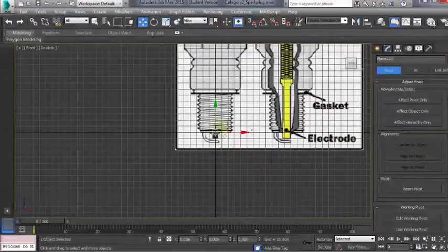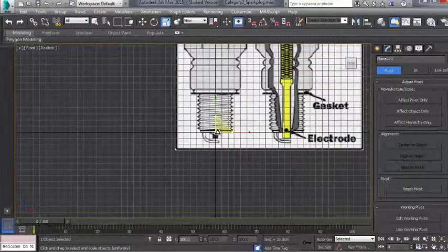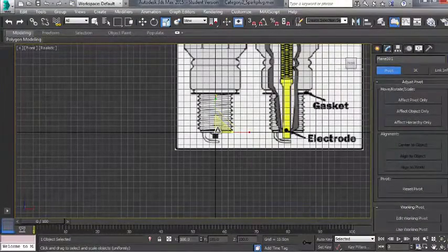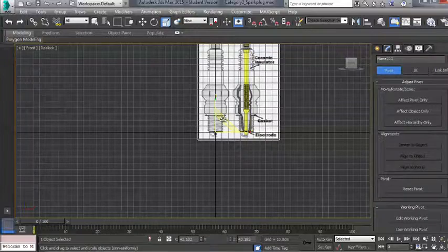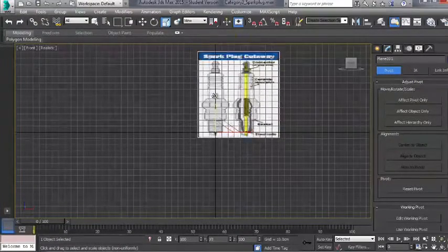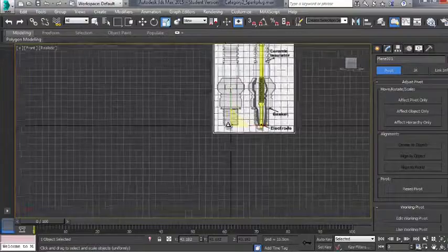So now with the plane selected, press R to select the uniform scale tool, and just make sure that you click so it's scaling along all axes. If you click on this line, it will actually only scale along those two axes, which, because this is just a plane, won't actually affect it. But if you are trying to scale it by just one dimension, you can actually do that by clicking on that particular axis. So I'm just going to Control Z to undo that scale.